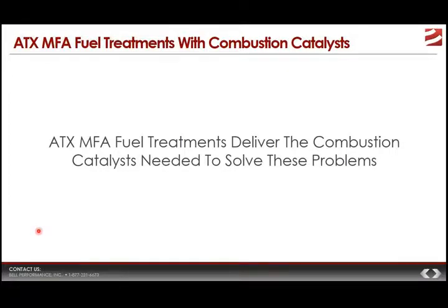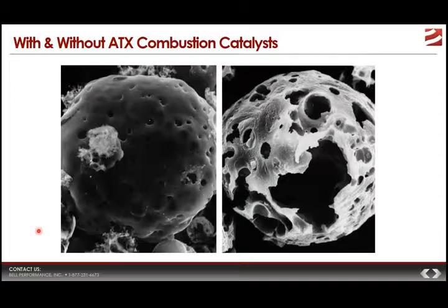combustion problems. So if you take fuel that was burned without a combustion catalyst, remember we talked about the cenospheres. This is what a cenosphere looks like. This is a carbon particle. Well, this has got lots of carbons in it, but this is basically what we could call a soot particle if you wanted. You can see it's got little holes in it, but by and large, it kind of looks like this. But when you take a combustion catalyst and you run it through the same process, you get something like this.